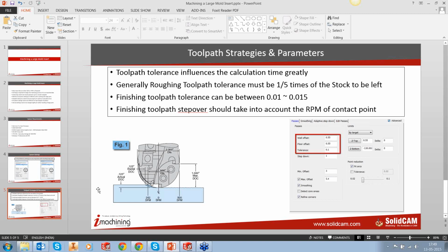So they come up with the catalog of the machine and show me that, look, the position tolerance says it's 2 microns. The repeatability is 1 micron, so why are you telling us that you won't get that tolerance? We have to understand that the repeatability and position have got nothing to do with your surface machining. The accuracy of your surface machining is always generated after you cut the part, you take it to the CMM and you measure it. That is what is going to come out from your machining. And that's the profile tolerance.